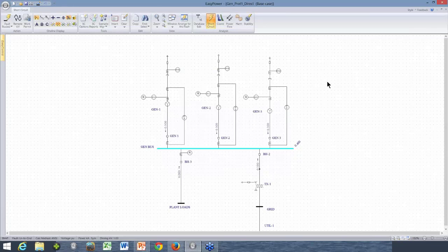The alternative is to have a common resistor, one grounded resistor, where you might have to switch the ones that you're not going to be in service, and you do see that done in some parts of the world. It's not common in the US. It creates operational issues because you have to remember to make sure you have the right resistor in the circuit. But just remember that just because I have 100 amps here in my resistor doesn't mean this fault current is going to be limited to 100 amps if the fault's in the generator.